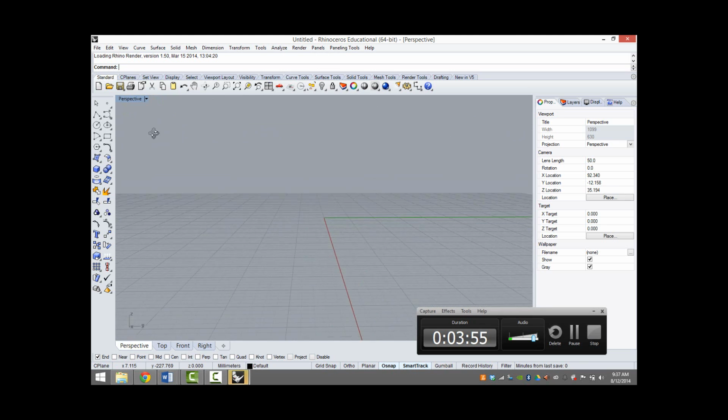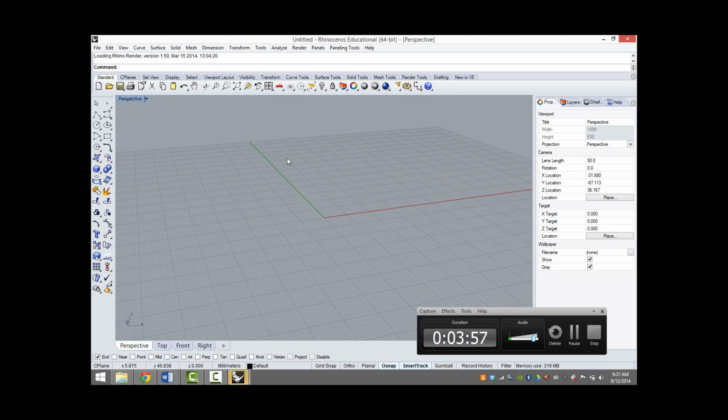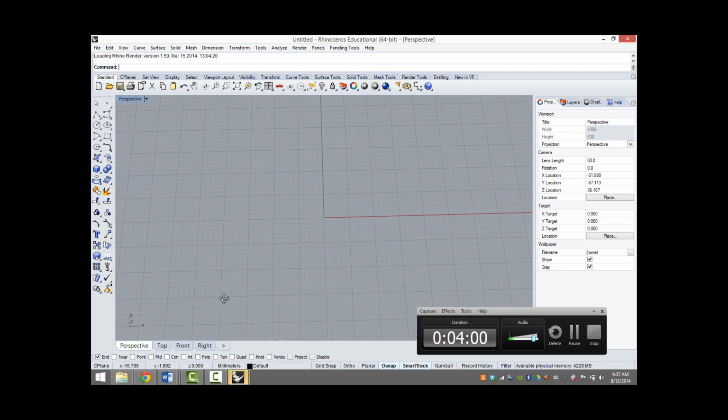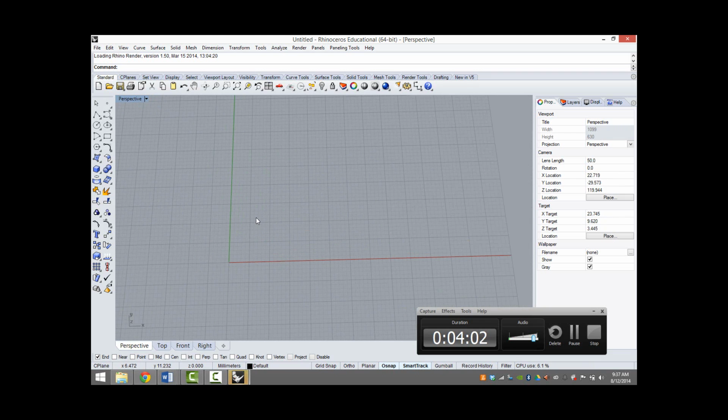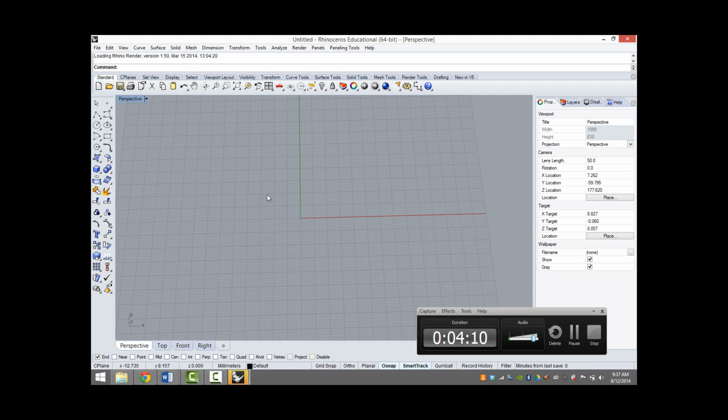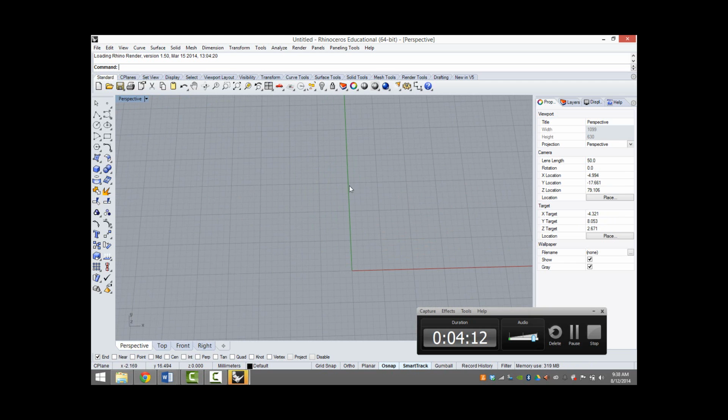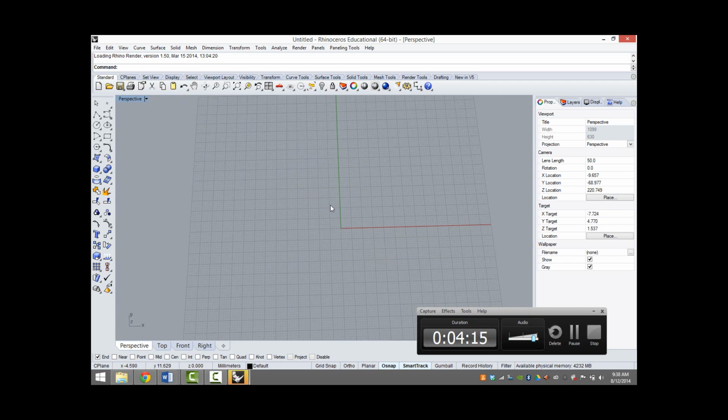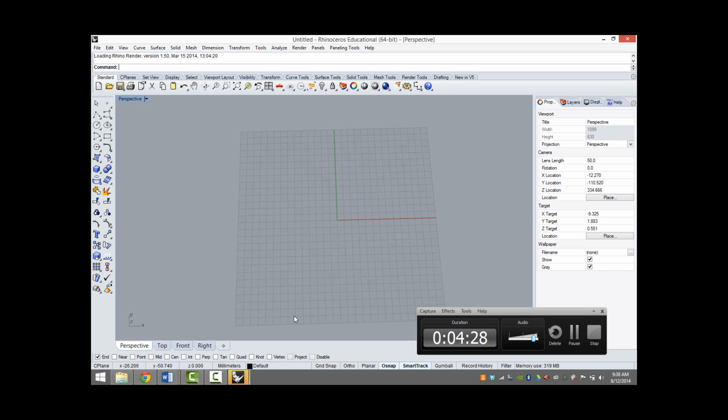Okay, so we open a new Rhino document, and we're going to choose large object inches. And what that means is you're creating a document, and the units will be inches, and it creates a grid that's scaled to larger objects. So things more of an architectural scale. If you're working at more of an industrial design scale, you choose small objects inches or millimeters, depending on your unit.